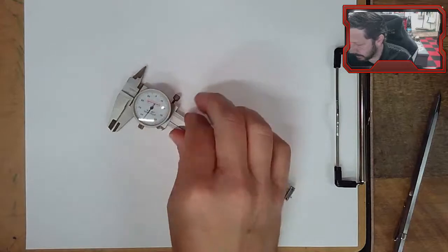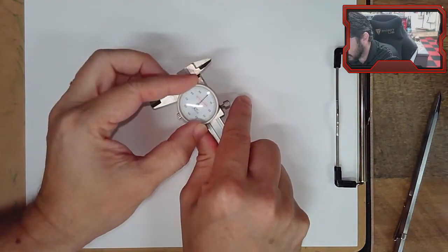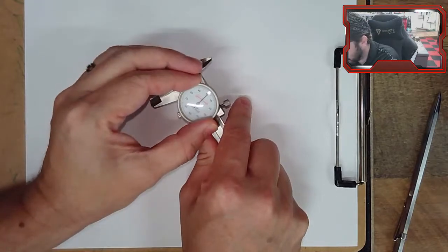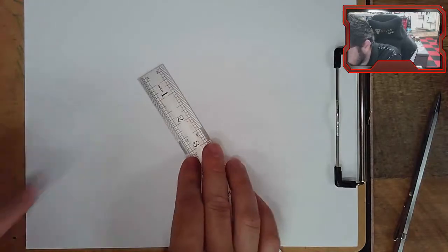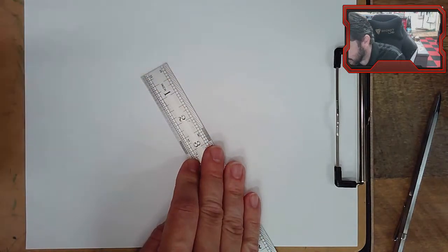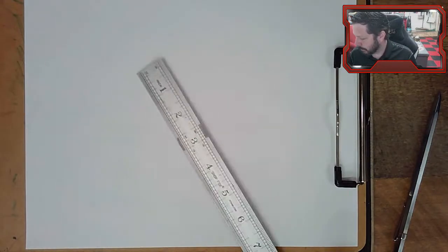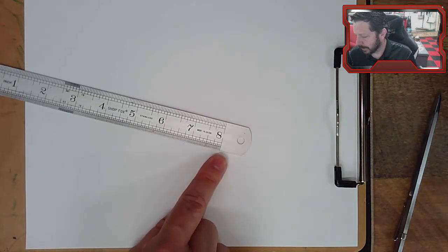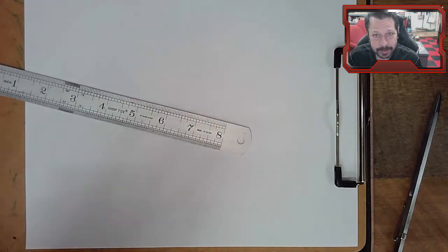Maybe that exists. There's always going to be some kind of bias, systematic error. You know, you didn't zero your calipers. When you closed them up, you didn't get the little knob dial to zero. It was off a little bit. That would be a bias or a systematic error. Maybe your ruler doesn't start at 0. Maybe it doesn't actually have the right end on it, or maybe there's some material at the end and then the gauge starts and you're not using it that way. Maybe there's an offset that way. So there's always some kind of potential for bias or systematic error.